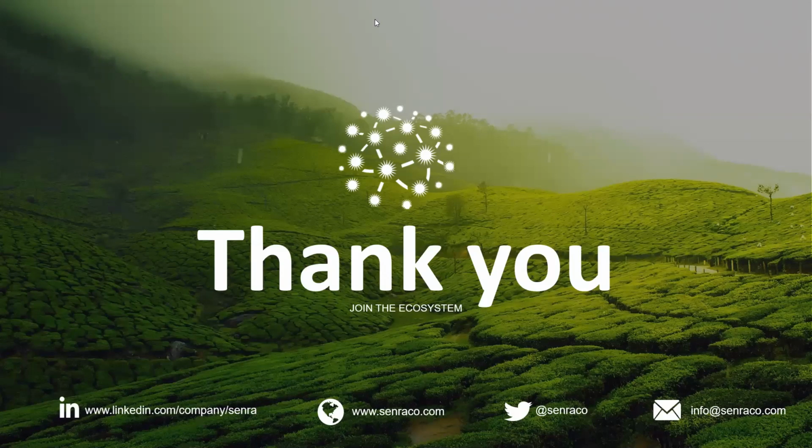FLoRa simulator, I remember it's on OMNeT++. I started using it, but it actually doesn't support ADR. ADR is one of the most prominent features of the LoRaWAN protocol that helps your end devices adapt the data rate or transmission power that they would want to use. I don't know if the OMNeT++ FLoRa simulator has been updated, but at that time it might or might not have supported ADR.